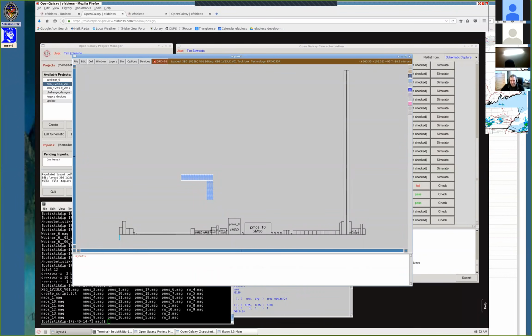It's not object-oriented, so I have not just created a rectangular object, which is what it would be in most layout editors, including something like Cadence, where each rectangle you drew would be a separate object and separately selectable. In this case, I have to treat the layers that I paint as having been painted into a mask. It matches the idea of the mask layers as they go to production. You've created these black and white designs on each mask layer to represent your layers.